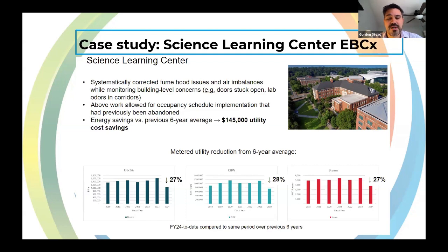And the number of classes, the turnaround that you have, and when you consider that that type of use of a fume hood is very different to a dedicated research lab with maybe one or two graduate assistants using a fume hood. Basically, it gets dirty. You got a lot of dust, a lot of chem wipes, a lot of little scribbled bits of notes which students have written on, get sucked up into the fume hood and lodged in the air valve. And what it meant was the air valves got dirty, they got out of calibration, and they were just pumping way too much air through the building.